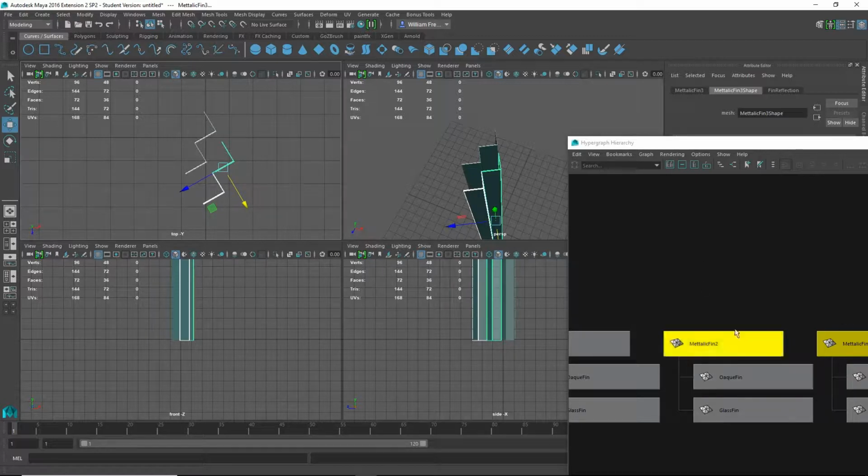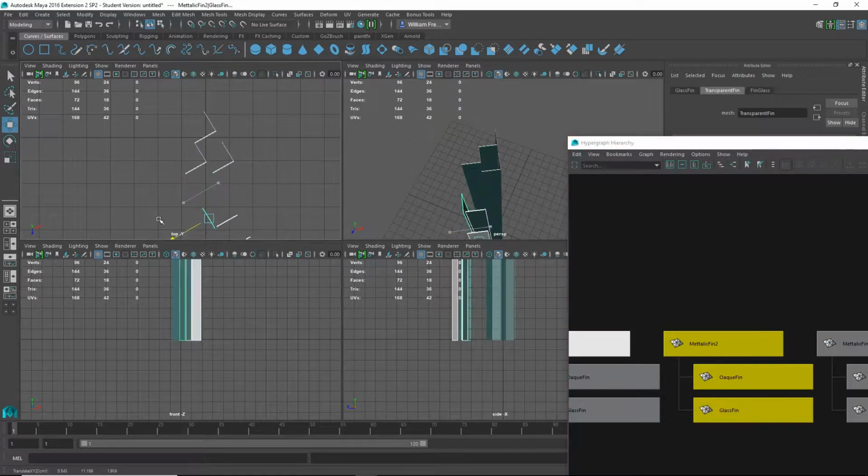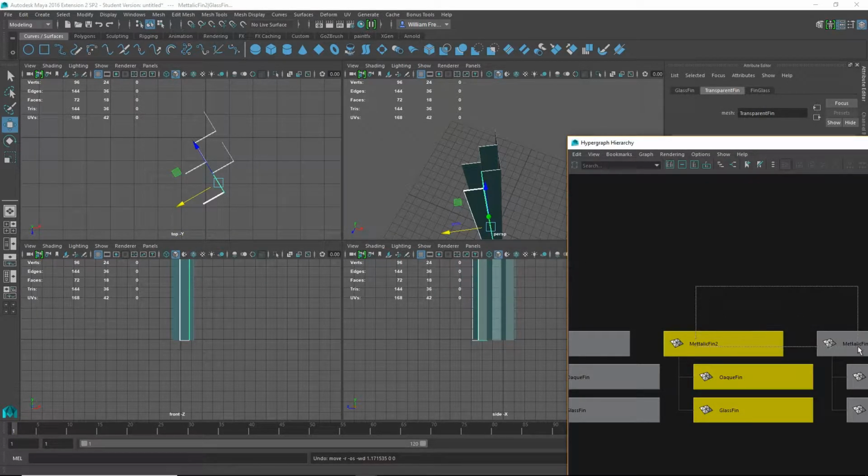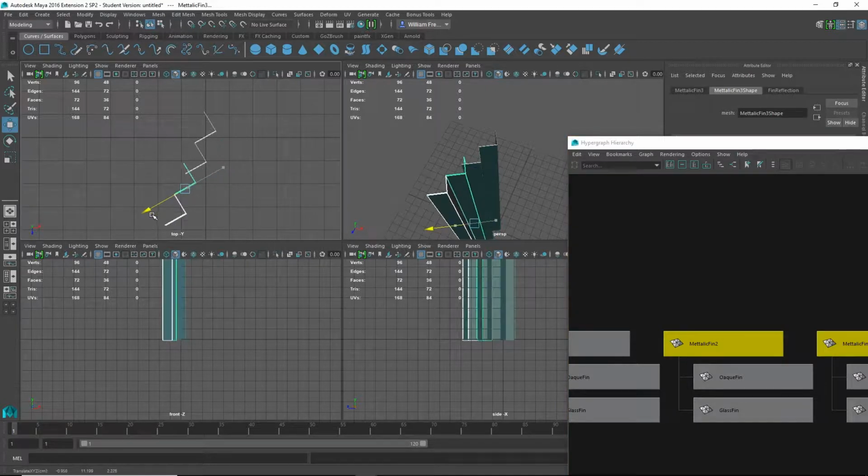But if I select everything, and I drag it, each one of these children has its own transformation matrix based on its parent, so when I move them in a specific direction, it's in an opposite direction, just to highlight the point. If I select that and move it out, you notice how it busts it up. So just select the parent objects and then position those.